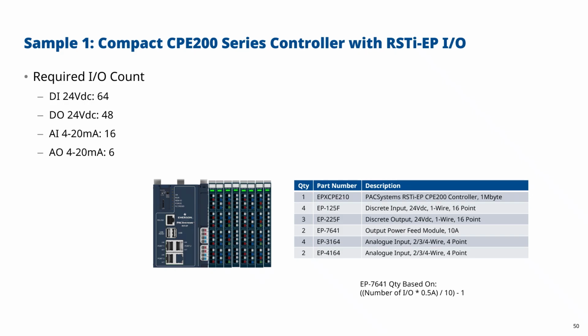So that's probably more than I need, but without knowing exactly what's required on the output side, effectively what I've got there is a 10 amp supply for the first EP225F, and then 2 more 10 amp supplies for each subsequent 225F. That's probably way more than we need, so you could do a power supply calculation, but at this level, that makes sure that I have more than enough output current for any possible output situation.